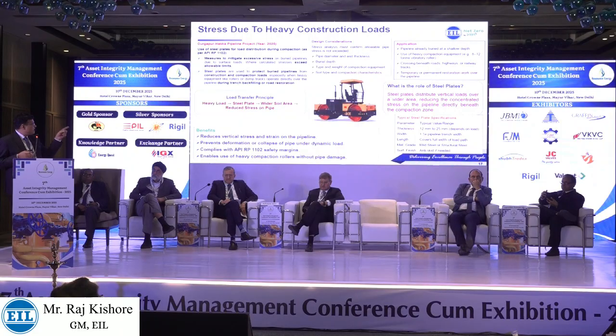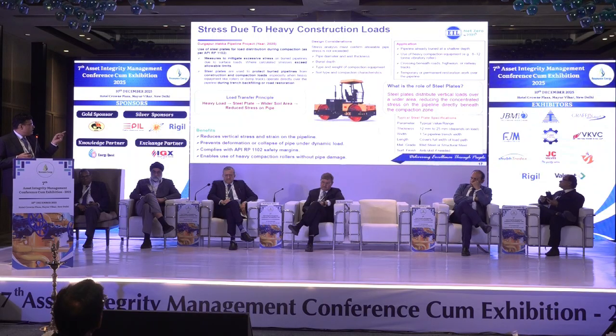We gave a steel plate. You put the roller on a steel plate, vibrate it and put the load, and it will distribute the load and make the pipeline safe. Accordingly, they did it and we completed this section of the pipeline.